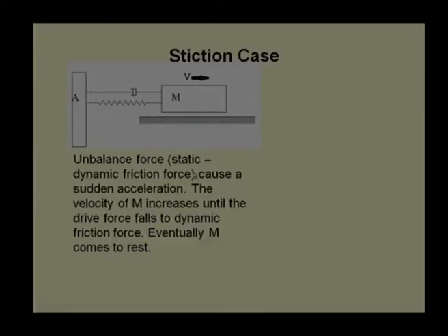What will happen? There will be a balance force. We have supplied a friction force equal to the static force, which is really required to start sliding of the block. Once sliding starts, the friction resistance comes down, is reduced.